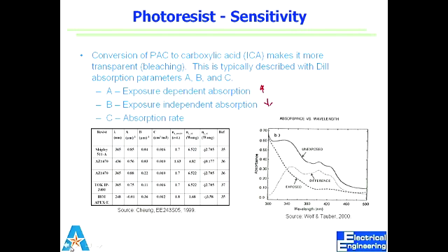But many times, for the same system, same wavelength, you need a thicker resist or a thinner resist, depending again on surface coverage, how many steps you have, or what is the smallest feature size you want to make. Because with thinner resist, you can make smaller features. But it may be more stringent in how you handle it, what are the conditions you have to maintain in the clean room and all that.